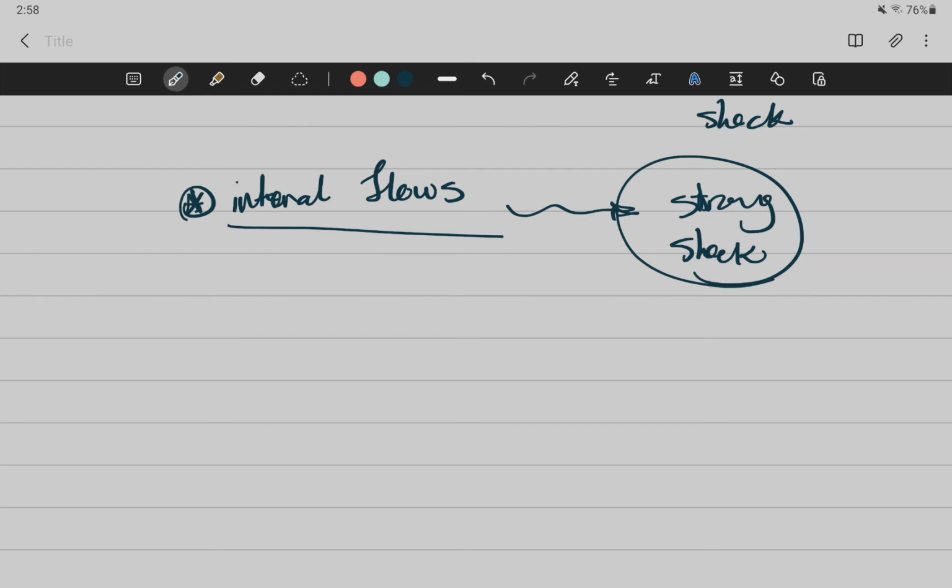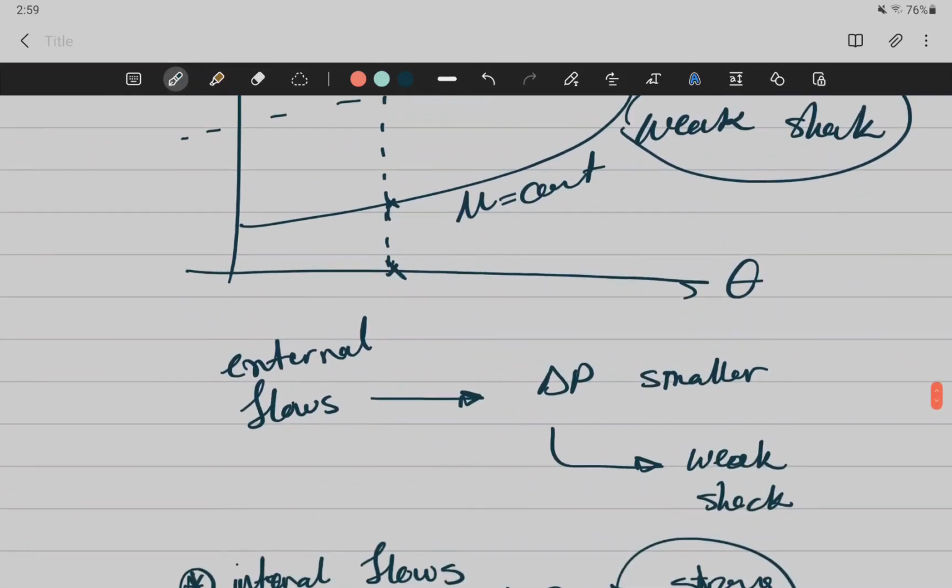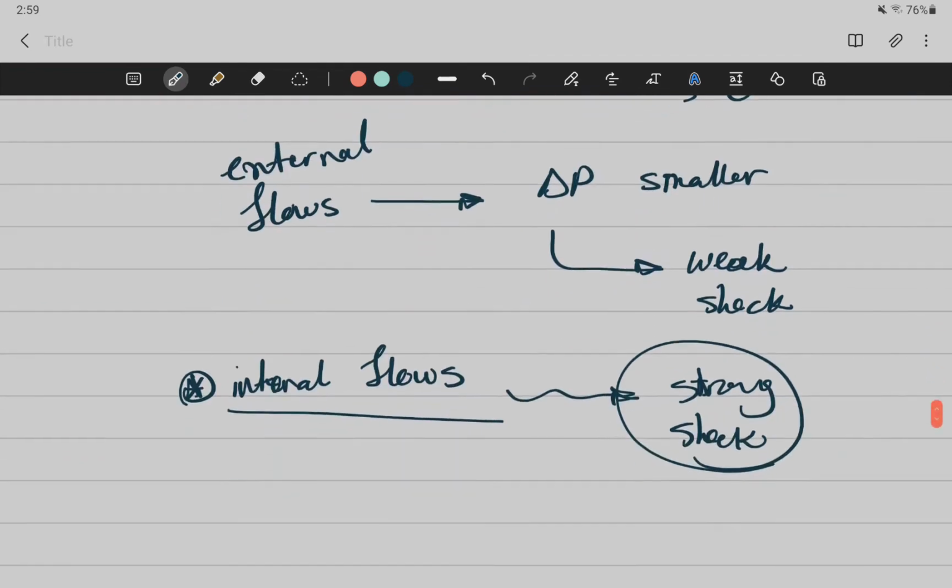But what is the solution procedure when it comes to oblique shock waves? Essentially, you have to determine either beta or delta, based on a given beta or delta or theta, and also a given Mach number. Then you find the normal component that's normal to the shock. You go to the normal shock table, find the M2, and so on and so forth, right? They definitely are going to be on an exam.